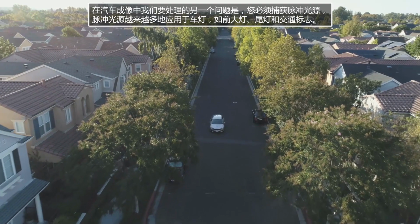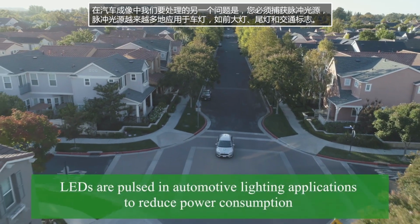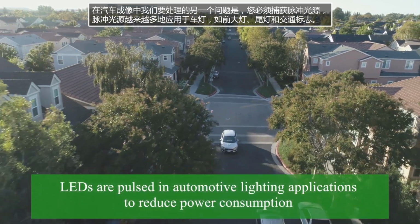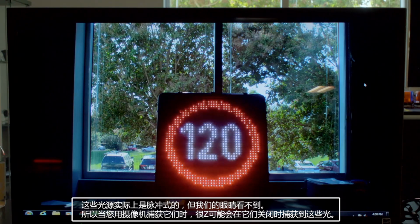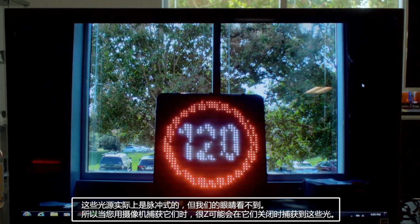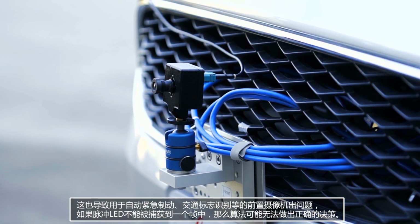Another issue that in automotive imaging we deal with is that you have to capture pulsed light sources, which are increasingly used for automotive lighting, such as in headlights, taillights, and traffic signs. These light sources are actually pulsing, however, our eyes do not see that. So when you capture them with a camera, you're likely to capture these lights at a time when they're actually off. So this can also lead to problems for front cameras, which are used for features such as automatic emergency braking, traffic sign recognition, and so forth, where if the pulsed LEDs are not captured in one frame, then the algorithms may not be able to make the correct decision.